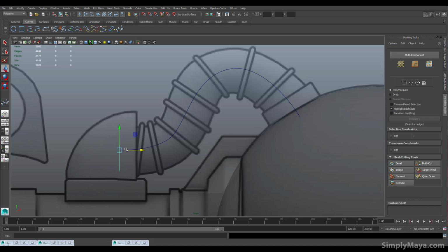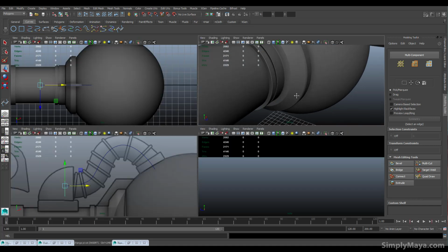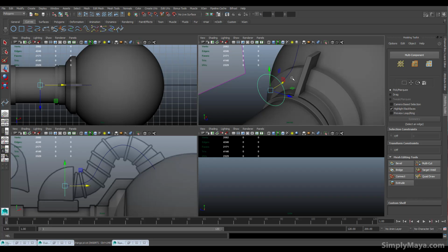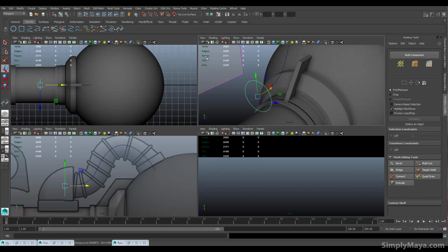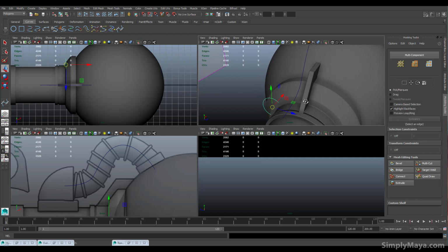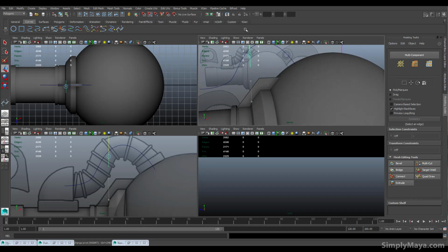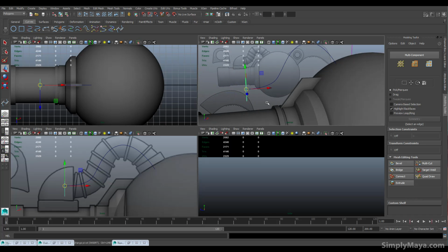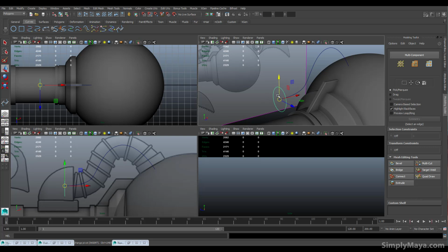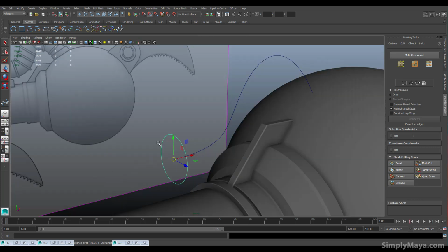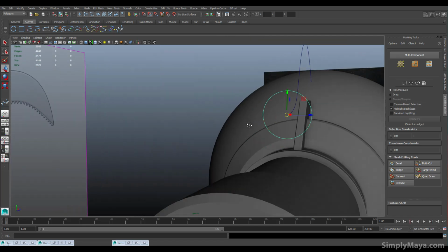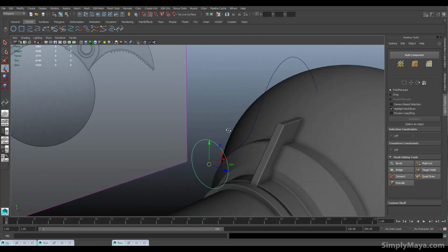Now if I want it in the exact center of my curve, which this will probably be pretty close, but let's say I wanted to make doubly sure, I can select my circle here, select snap to curves, and then come in and grab the snapping point. Oops, I've snapped to a curve over there now. Come here, you. And I'm just going to snap this onto the curve, which can sometimes be a pain in the backside. There we go. So that's snapped it to the curve. I can't pull it any further back, and that's now right at the center of the curve. So yeah, I can just show you that that's spot on.